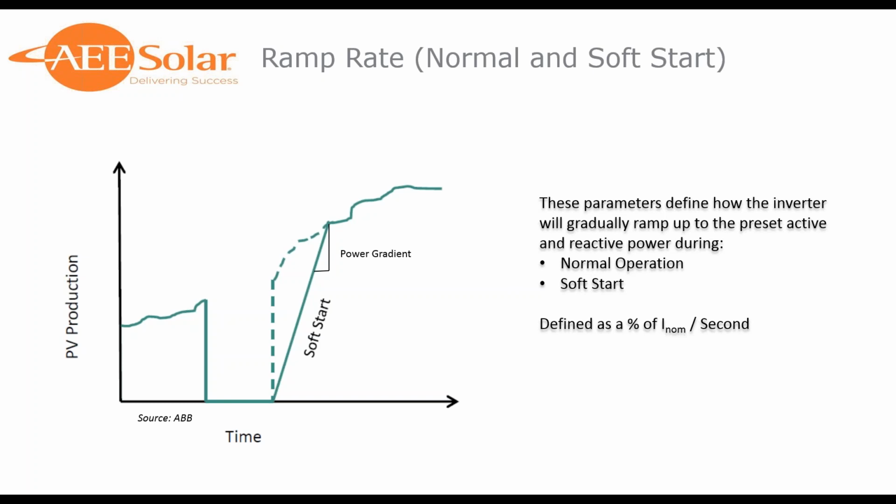So now we've programmed in the ability for a utility district to define this ramp rate. As a percentage of nominal current per second, how quickly is it going to accelerate? And again, there are 2 operating modes covered up here: normal operation and soft start. Normal operation refers to active inverting, how the inverter ramps back up when more array wattage is available.